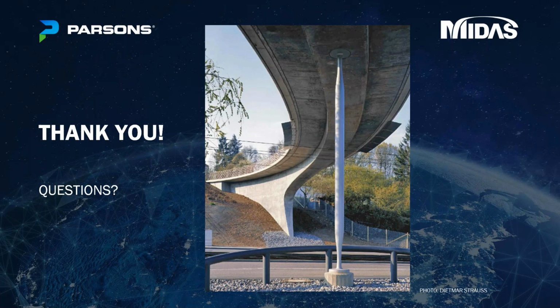So when you have a long span bridge and a major structure, say cable supported, you can do this with the piers. And I think Christian Menn showed that with the Sunniberg bridge. When you want to control the movements, you can do this with the piers when they're slender enough. The problem is what happens at the abutments, because at the abutments you have to transition to the soil. So you can have abutments moving as well, but then where are you taking out those movements? If the abutment shall not move, then you need to have the bridge moving vertically or laterally.